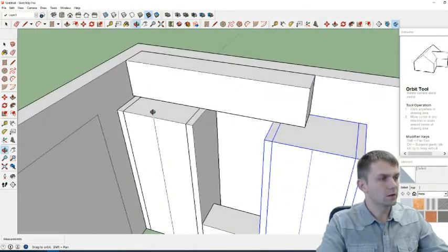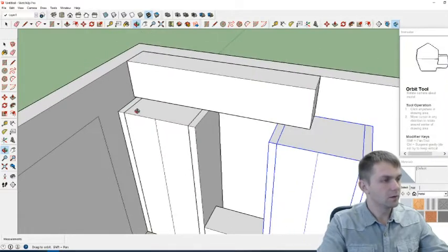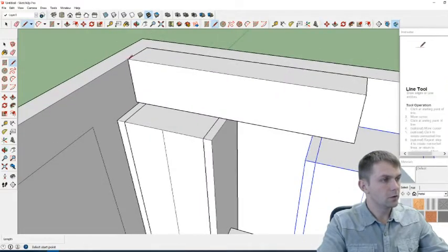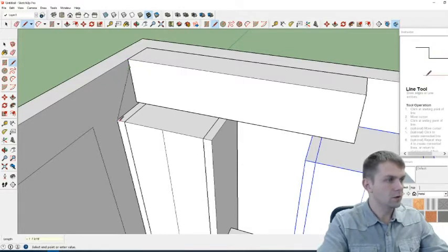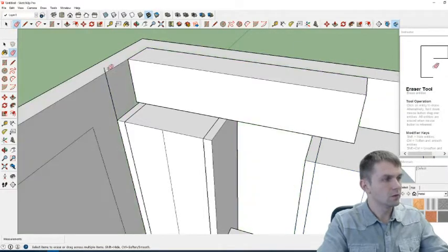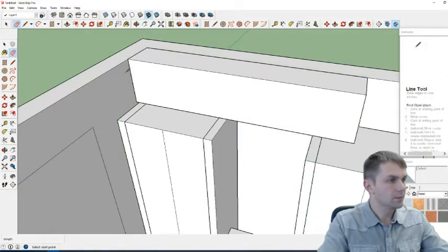And we basically have this kind of look. Now to close this bulkhead, we can also add cabinets on top. So we'll go 2-inch, 3-inch spacer. We want to line it up. You see the blue line is giving me a horizontal, oops, Control Z to go back.